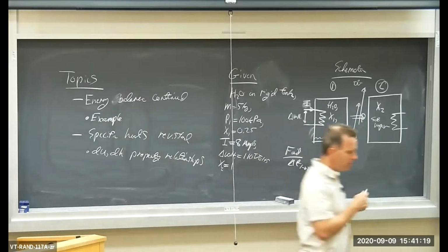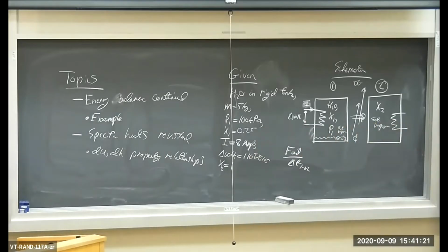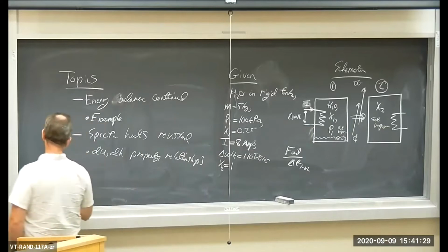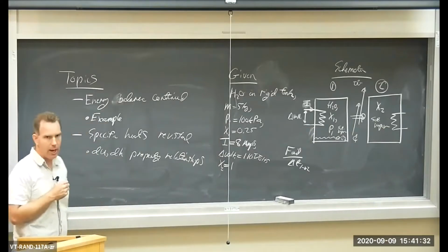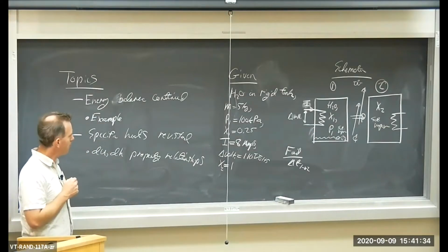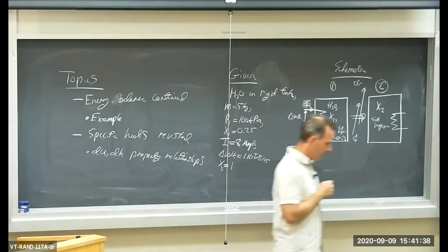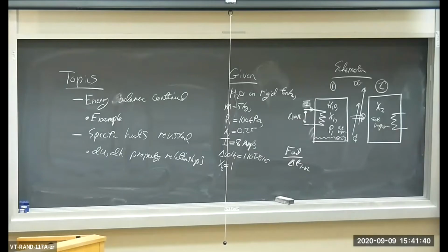This is a bit different problem than what we've been used to before. Previous problems used an ideal gas, so we were able to use the ideal gas law and ideal gas property tables. This problem involves H2O and a two-phase mixture, so we're going to have to use saturation tables to calculate change in internal energy and such.